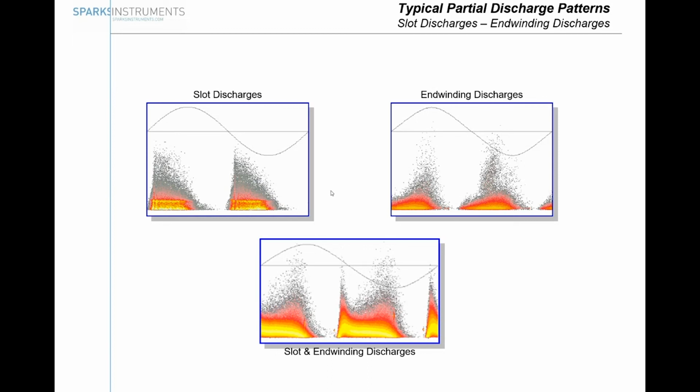So basically, as I said, I understand evaluating partial discharges is very difficult, especially for customers who are not very familiar with that and don't do it on a regular basis. For that reason, we have provided in our documentation a catalog of typical PD patterns and their defects, which helps to identify the source or the root cause of the partial discharges. I also suggest the customer purchase the IEC standard I was referring to before in this presentation, because at the end, in the appendix, you can also find a catalog of typical PD patterns which can occur in machines.